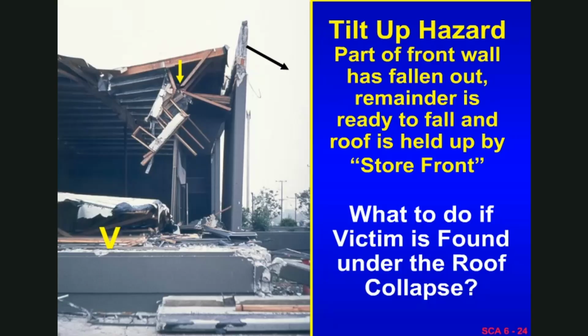As an example, if the victim could be removed within a few minutes or less than half an hour or so, one might do nothing more than minimize the exposure of only having a few people getting to the victim and having someone monitoring the rest of the structure. If it took a considerable amount of time, then one might have to look at shoring and raker shoring the wall and perhaps vertical shoring the roof. So it always depends on the victim. It depends on how long it might take us to get to the victim. It depends on the risk we're willing to take for a live victim versus the risk we're willing to take for removing unviable victims.